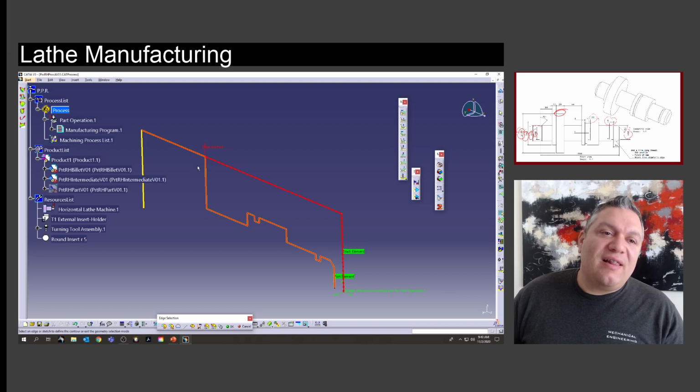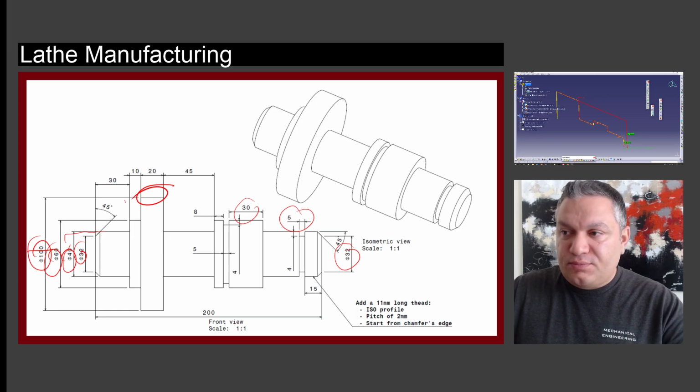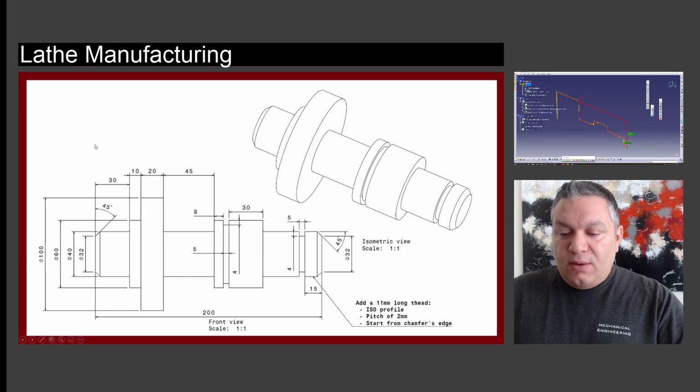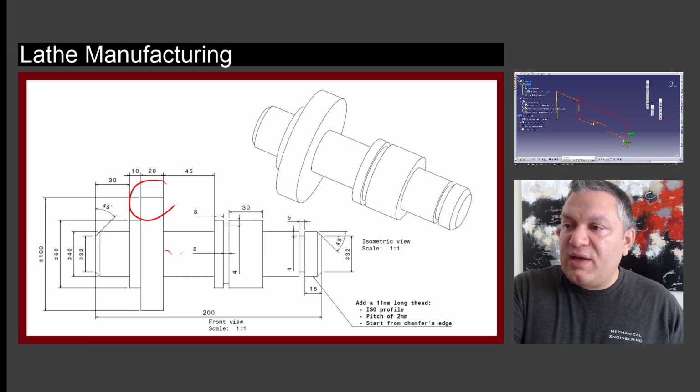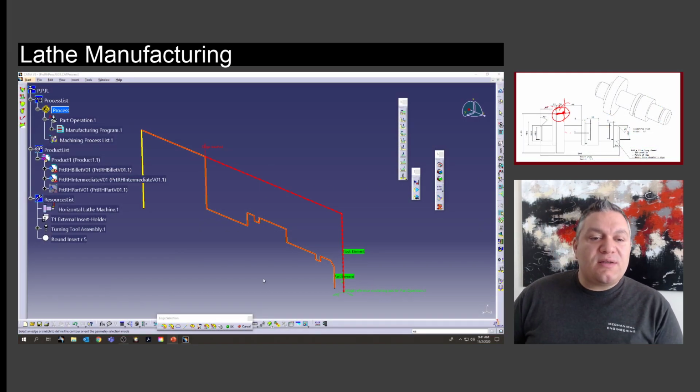I should have left this one common between both of them so that I don't have any bad manufacturing in here. What I'm talking about is in this location, I should have left this profile in both of them, and I should have finished it in both of them. Because right now I'm gonna come and finish here, and from the other side I'm gonna come and finish here. So this might leave room for something in here. So what we're gonna do is over travel from the other side. This is how we're going to solve it.